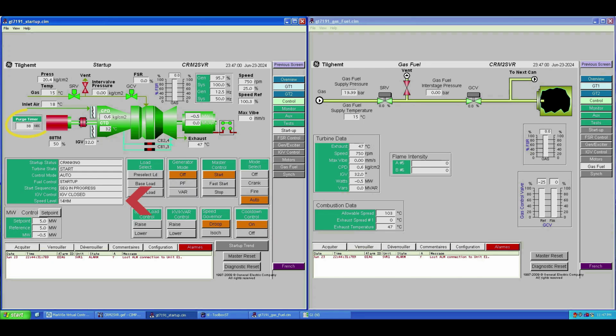The L14HM signal, or the completion of the purge cycle, L2TVX, enables fuel flow, ignition, sets the firing level FSR, and initiates the firing timer L2F. This timer lasts 1 minute. If no flame is detected by the end, the turbine will automatically trip. The ignition timer is not displayed on the HMI.